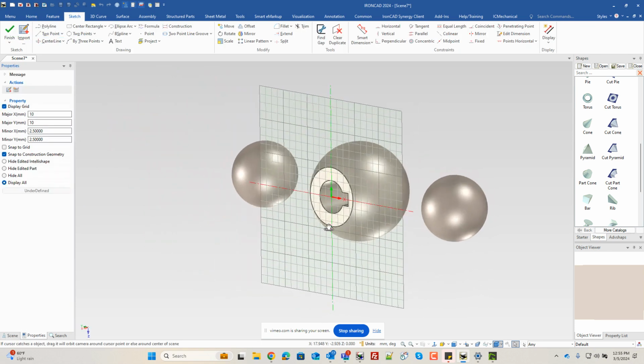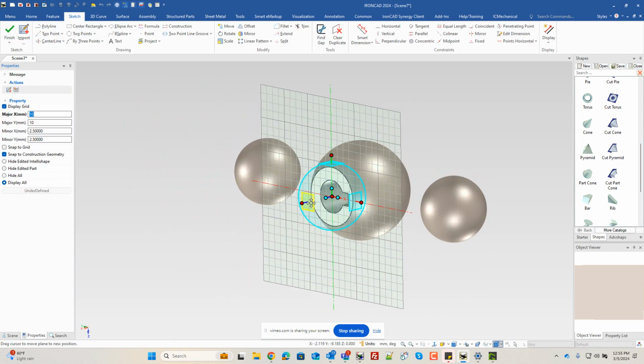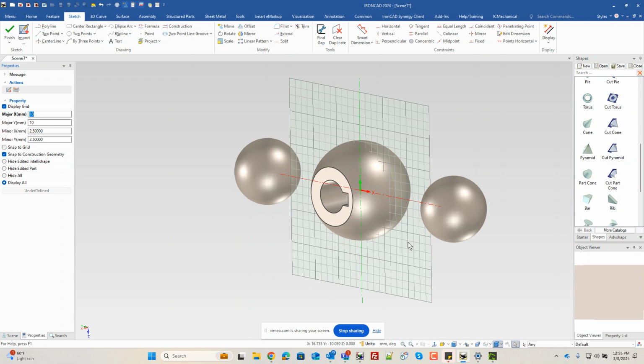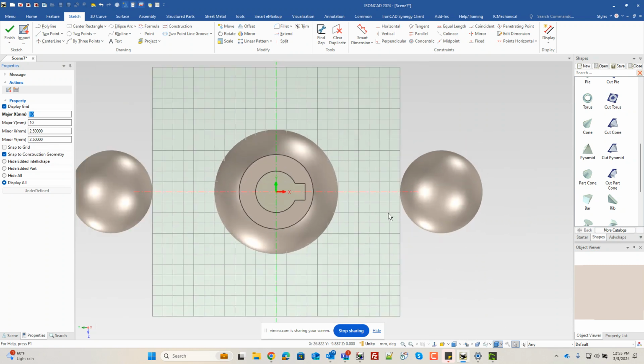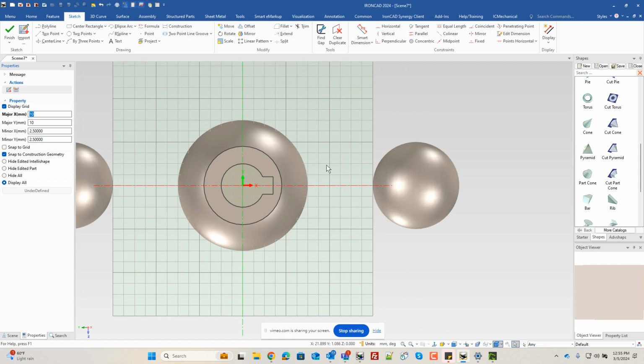And what we want to do is move this back to the center, so we can just turn the TriBall on, lock our axis to the center point of that to get it in the right location. So now that we have that, we can look at our plane and our profile. And what we're going to do is basically create a spin for this thing. So what I'm going to do is just draw some of these lines because we need to know where these intersect, and we know there needs to be one that's 4.5 and one that's 6 inside of here.